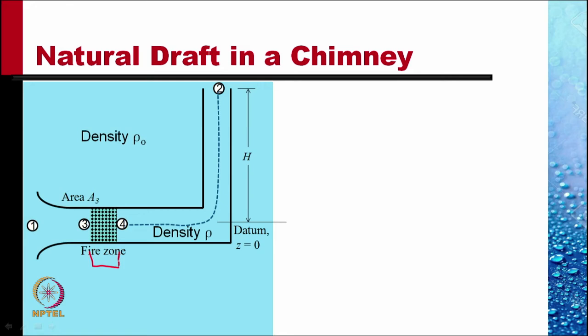Let's apply Bernoulli equation between point 4 and point 2. Point 4 just after the fire zone, and point 2 at the exit of the chimney of height h.